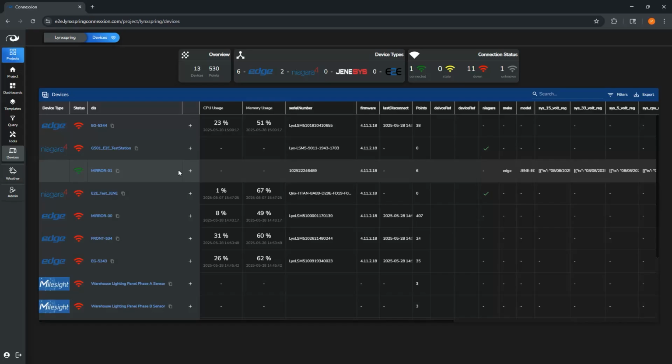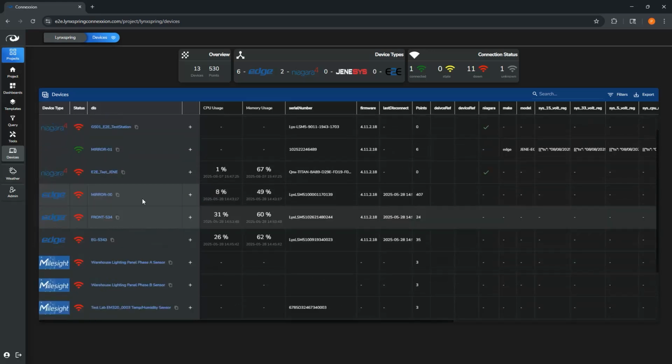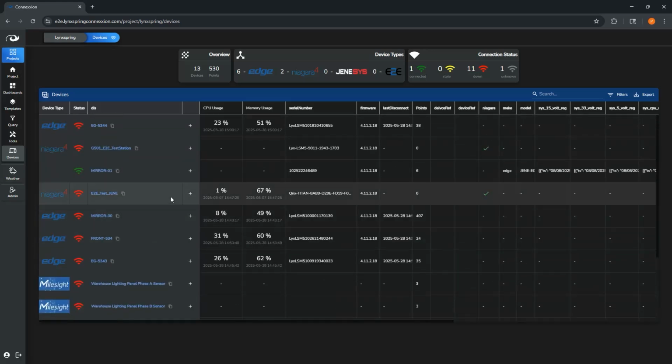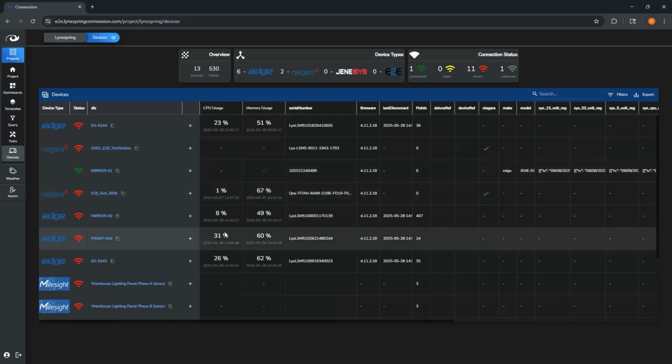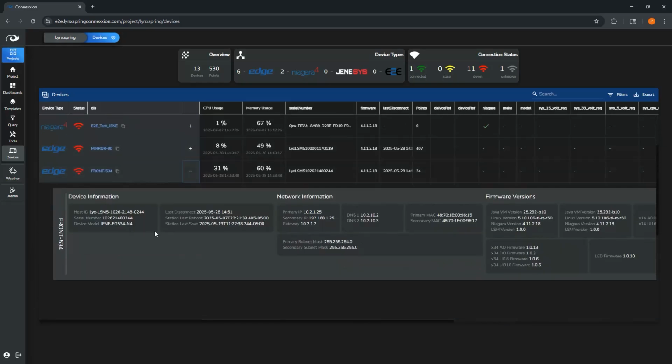You can get the information about, like I was saying, your firmware versions from Niagara, your operating systems. You can see information about the last time your station was rebooted. There's all kinds of different information here for you to centralize the management of your fleet. So that's the main concept behind the device manager. And as time goes on, we're going to continue to expand on this. You do see a couple other sensors here that we've been working on trying to put together. There's MileSight. These are LoRaWAN sensors. This is stuff that is in beta, so that's not really out there yet.